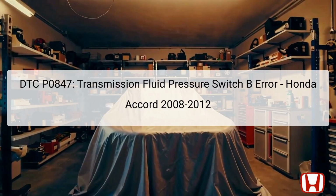The DTC P0847 indicates an issue with the transmission fluid pressure switch B for the third clutch circuit. This error signals either a short circuit within the electrical system tied to the pressure switch, or that the switch is malfunctioning and remains constantly activated.